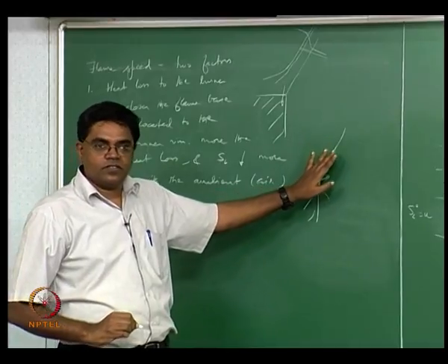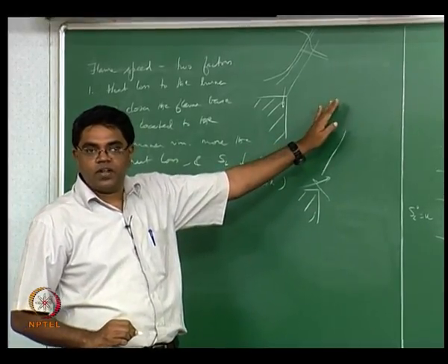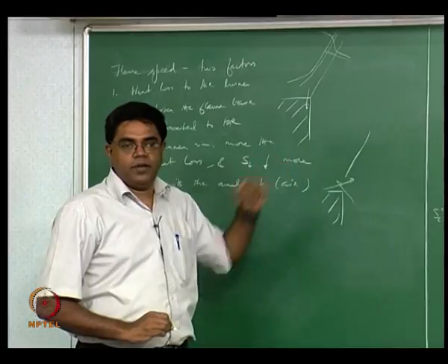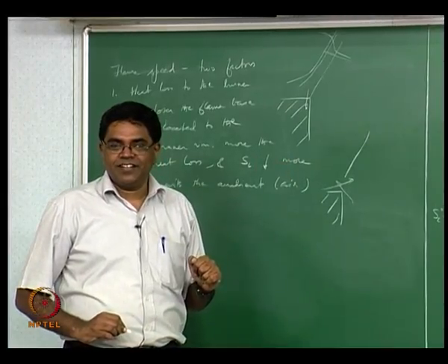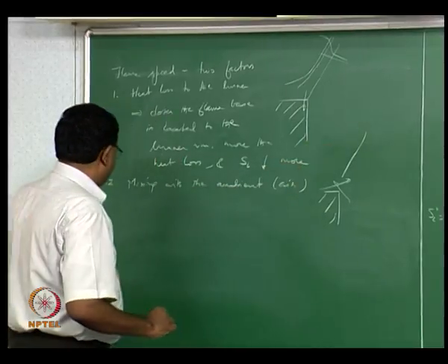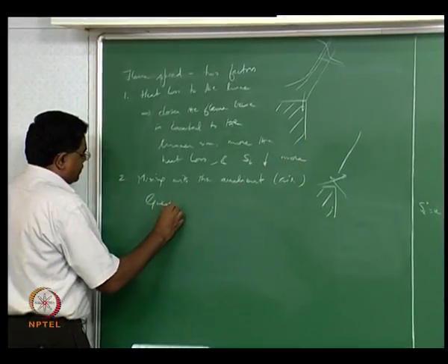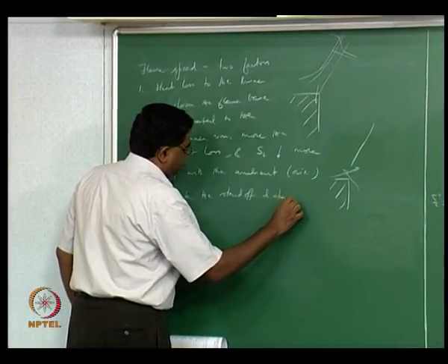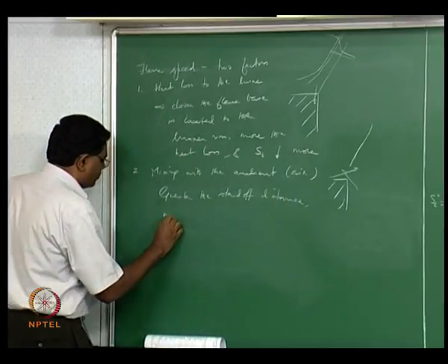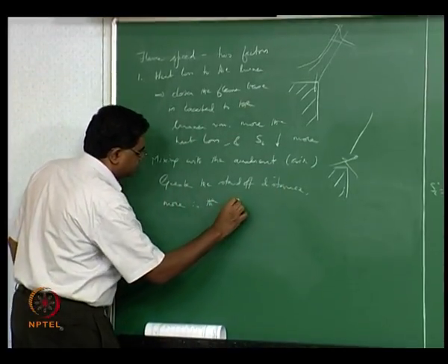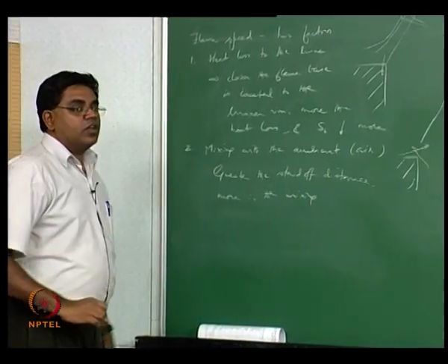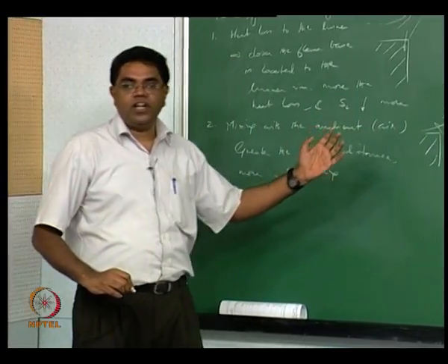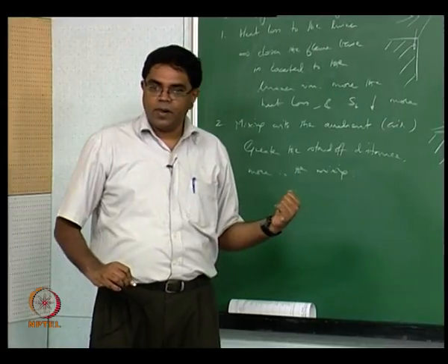What's the consequence of this for the flame speed? That's really the question we have to ask. That depends on whether the flame is a fuel rich flame or a fuel lean flame, right? So let's just record this: the greater the standoff distance, the more is the mixing. And the question is whether that mixing is going to increase or decrease the flame speed.